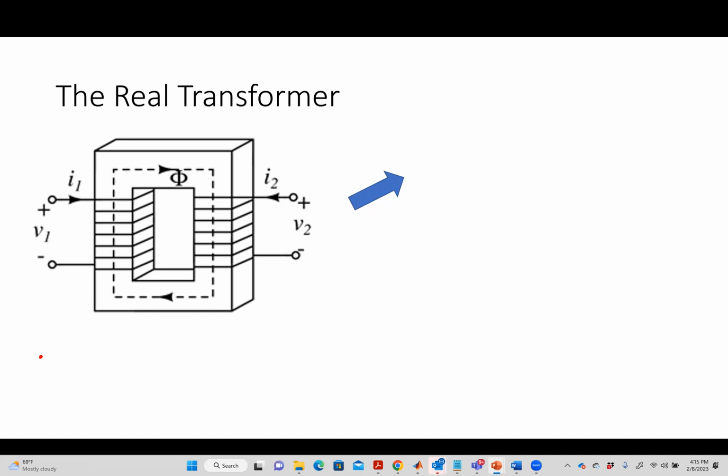Let's forget the losses for a second. The losses deal with what's going on with the conduction and everything. But if I talk about the magnetic parts of this circuit, what about the core? If the core is ideal, what did that mean about its reluctance? Zero. So a real core is basically going to have a mu which is much, much bigger than mu naught, but it's not going to be infinite. We said for a real magnetic material, maybe it's 10 to the 3rd to 10 to the 4th times bigger than mu naught.